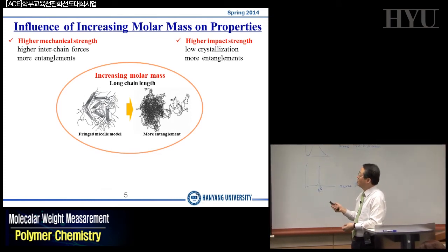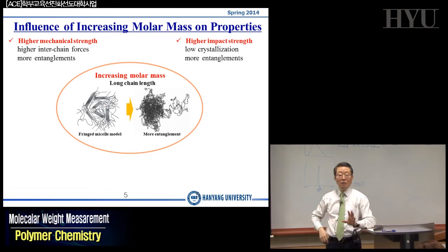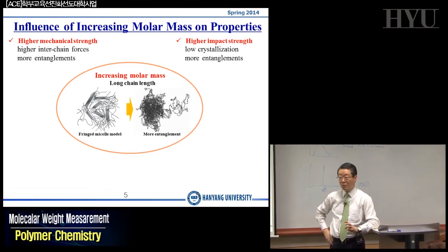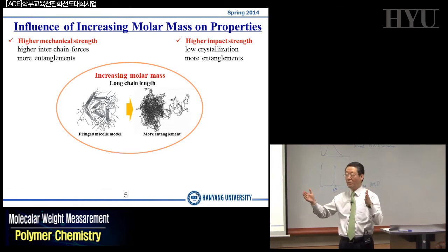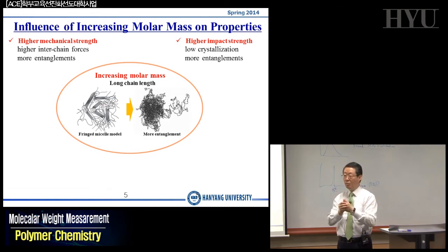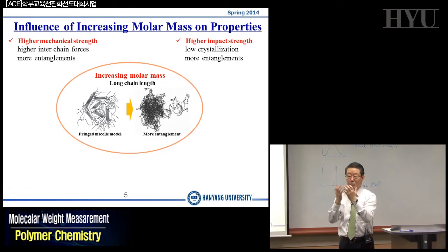Impact strength could be applied in the case of plastic as well. If you have a certain plastic, which is usually a glassy polymer, but you add rubber to your glassy plastic, your polymer will have a higher impact strength because rubber absorbs the energy. Impact is an energy, and you absorb the energy, so the material with the glassy and rubbery parts will have a high impact strength.